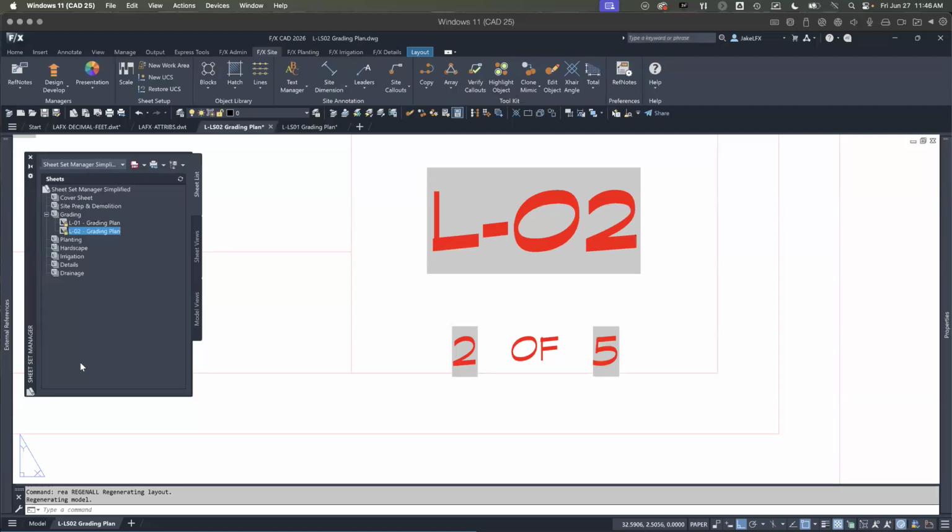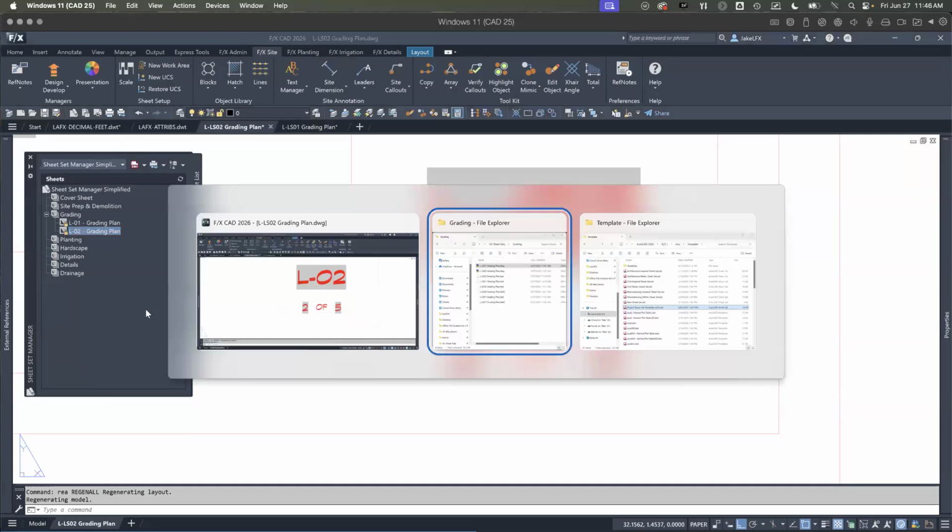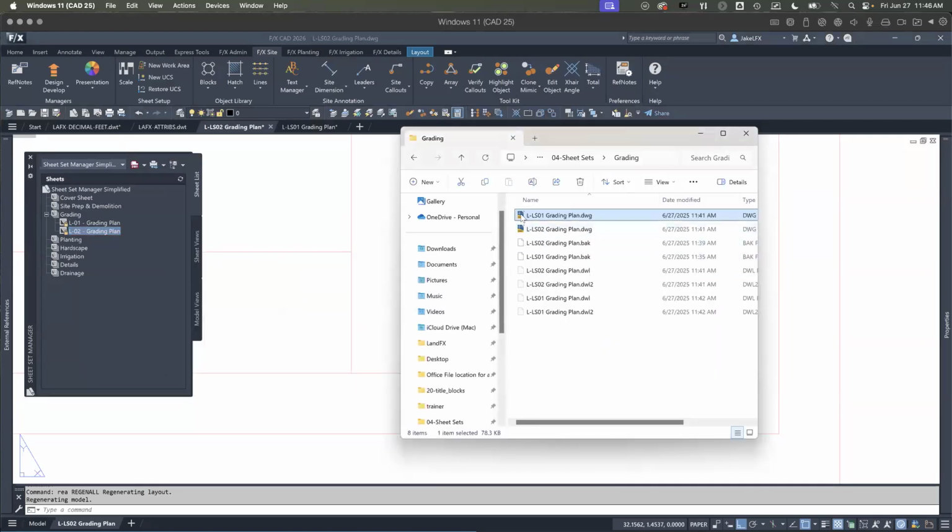And then the other biggest one I've personally experienced was computer performance: every layout in a single drawing slows that drawing down exponentially. So adding the 10th layout is way more slowdown than adding the second. And I've actually seen that happen. You just sit there and you're like, ah, my computer's slow. I need a new computer. I need the most souped up model I could possibly need. And it's like, no, it's not. It's just the drawing organization practice that is causing CAD to take up so much of your computer performance. I know line type scale was another reason, but there's so many benefits. Did you have any other thoughts?